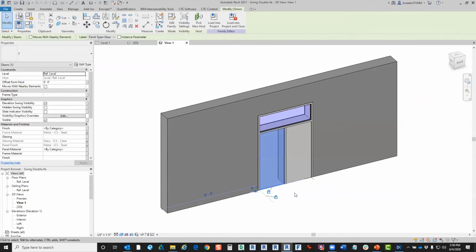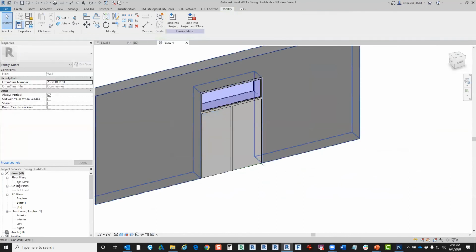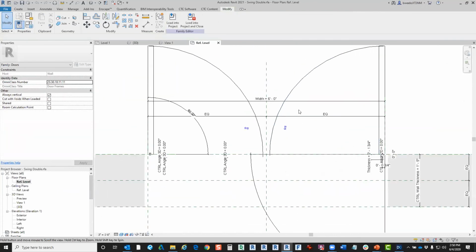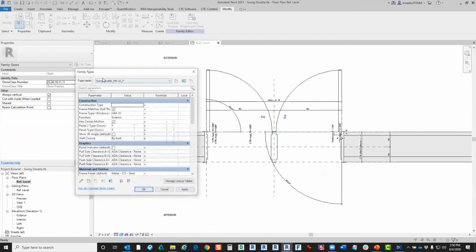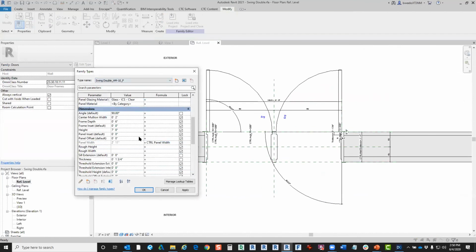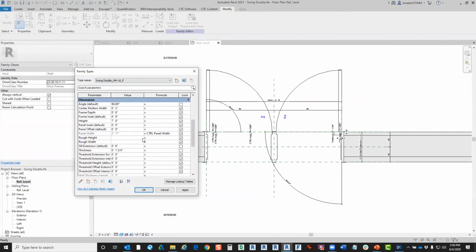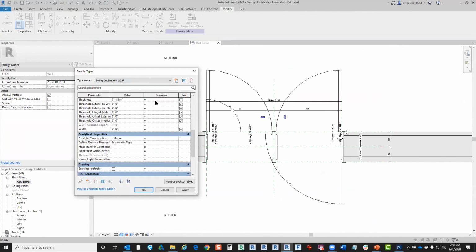So for example, this is my F style door, and it's set to the 6 foot wide that we set. Then I would create a duplicate, because you can see I can scroll through the family types, and the panel width is controlled by the overall panel width, which is there. Let's say I want to create, maybe a double door is a bad example, because 6 foot is pretty standard. But let's say I want to make an 8 foot wide door. Maybe we're working in a convention hall, and they need an extra wide door with a removable style to get some equipment through.